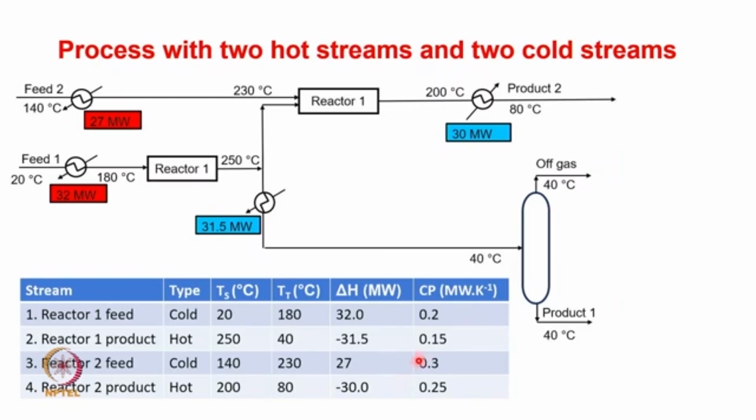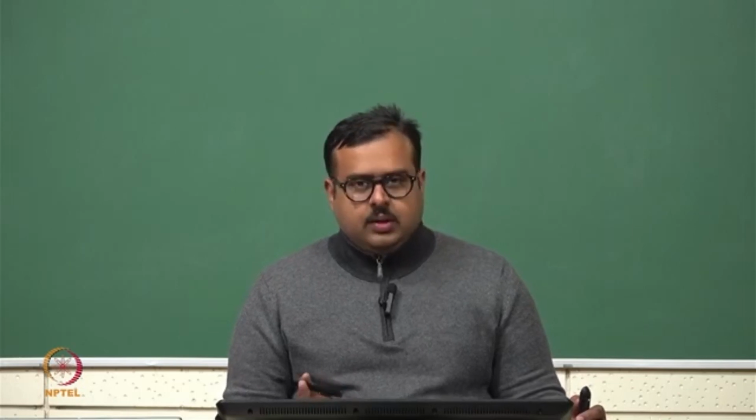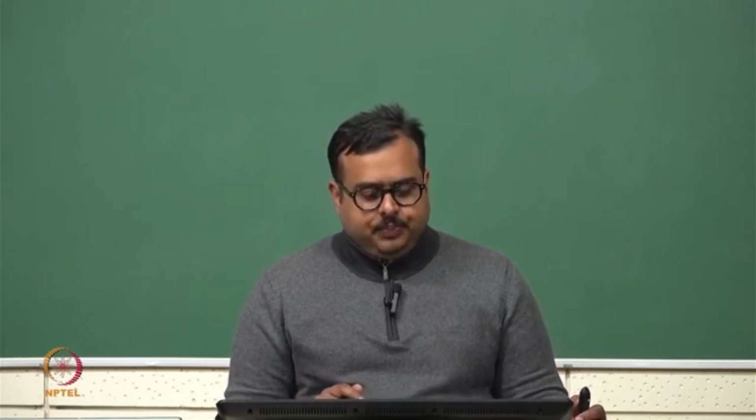So now we have multiple aims in this part of the exercise. Try to write, or rather draw, the composite curves. Identify what is known as the pinch point. If you identify the pinch point, can we use the concept of pinch point to redesign the network so that maximum heat recovery can be obtained, and how to do that systematically. So that's what we are going to do in the remaining part of the lecture.